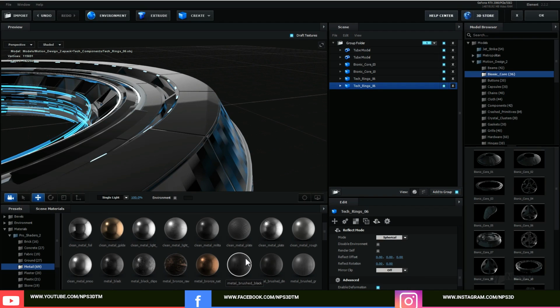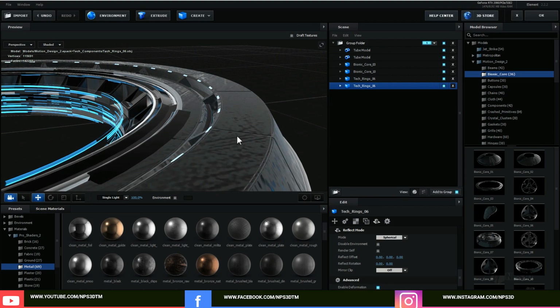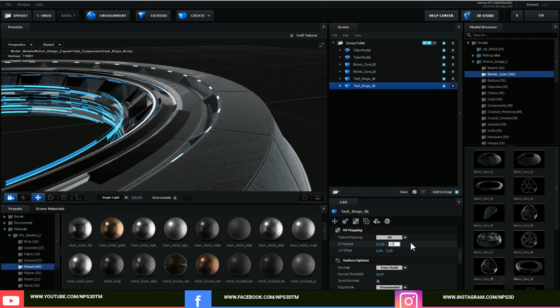So basically I want a texture which includes more roughness, but just uncheck this rough textures to see the texture correctly. One more step you have to apply for some other models like this, take rings. Go to the UV mapping and just tile it to something around 12 by 12, right? Same for this one. Because we want some close up.